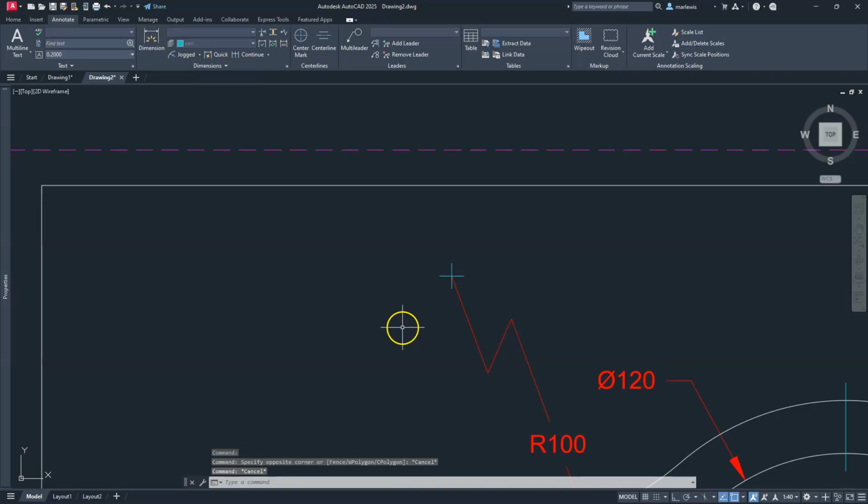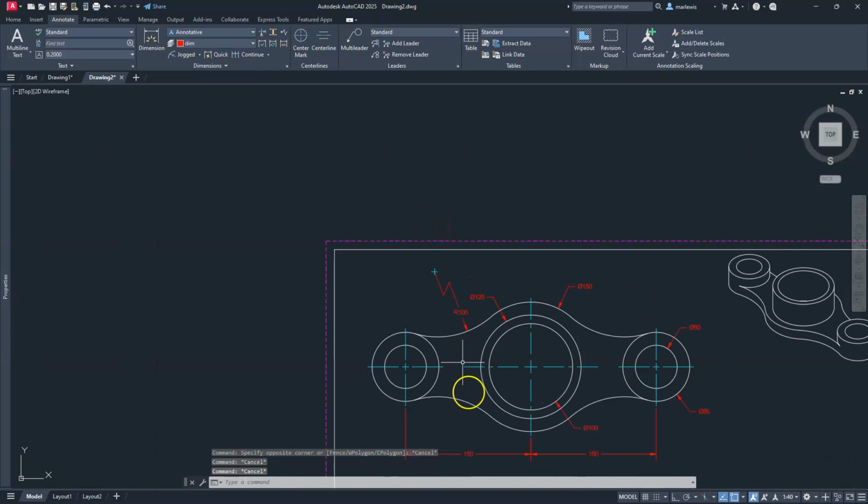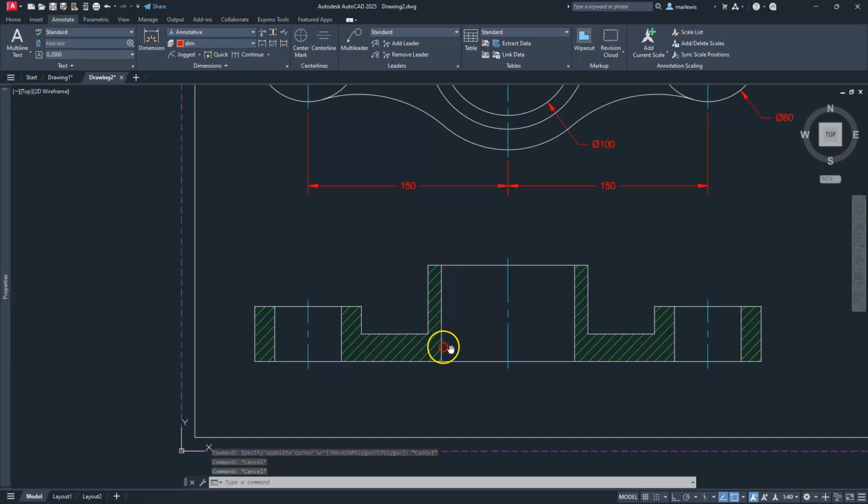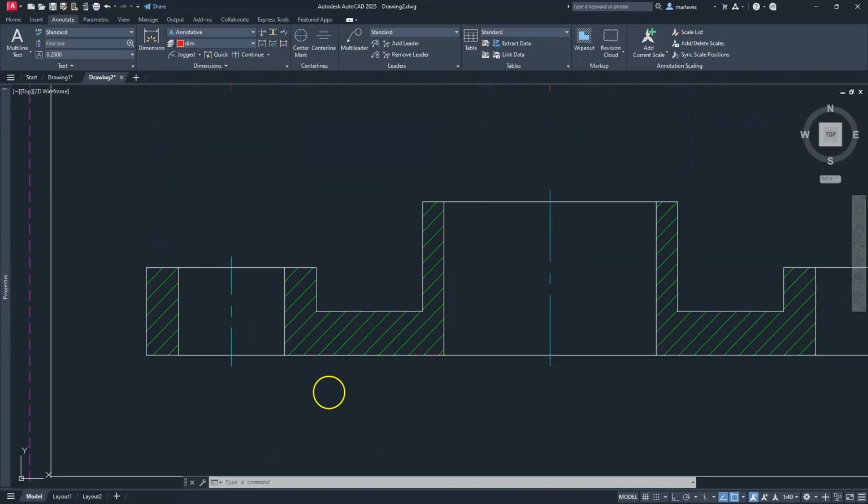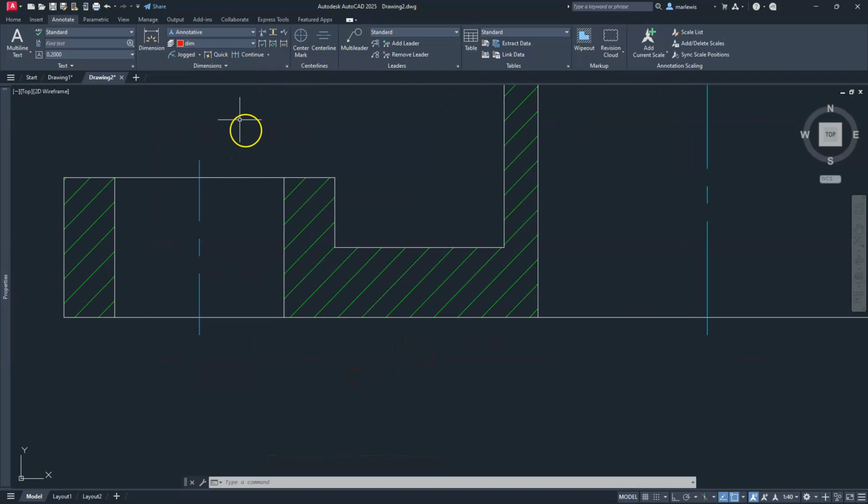Okay. Let's come down here to the bottom. Let's go ahead and add some more dimensions onto this. We're going to add a linear dimension here. So that's going to be DLI, enter. I'll select that midpoint to here, and then go to here, right? Let's go ahead and select this 20 here. Grab the center grip that's sitting on that 20. Go ahead and pull it down, and then come back this way.